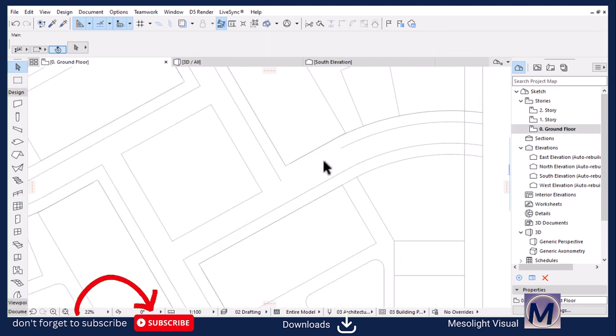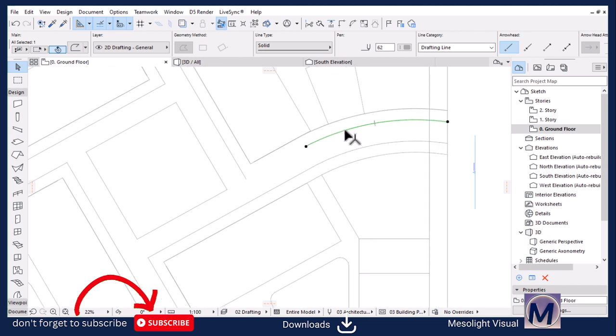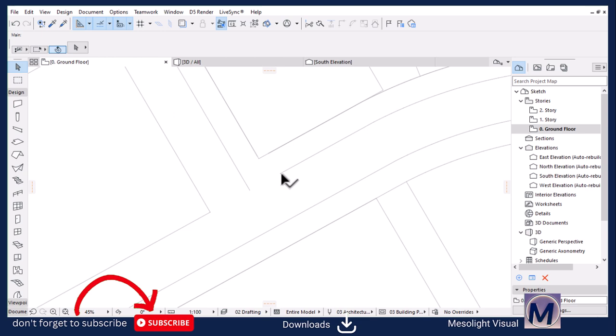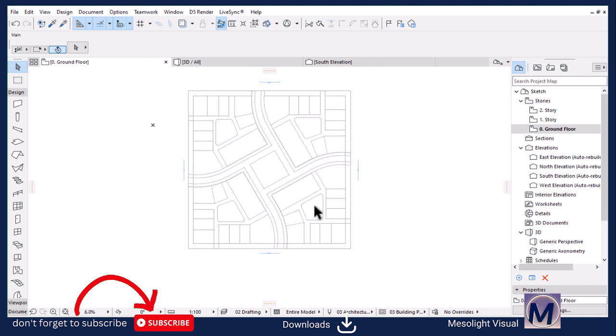Perfect. We have a little bit of an issue here. I don't know what happened. Maybe when I was trimming, it disappeared. So I can delete this line. Or let's just select this and stretch or offset the edge. Make sure we are picking a copy. I'm going to hit Control to add a copy and then just place it there. Then I'm going to select the ones that are condemned and then delete them. So these ones I'm going to fillet. Perfect. So now I have a continuous side, as you can see.